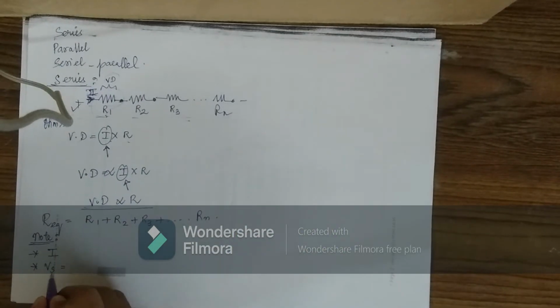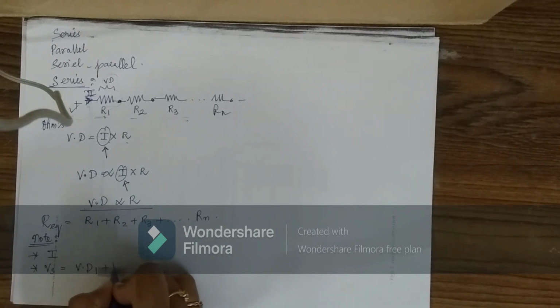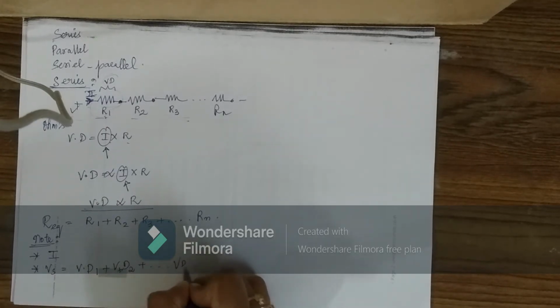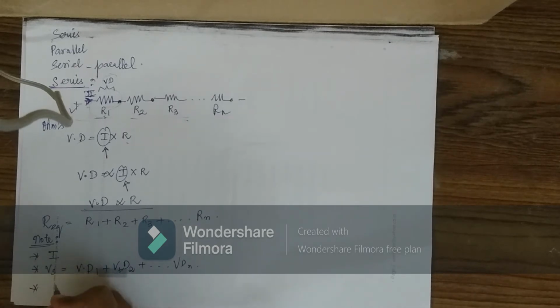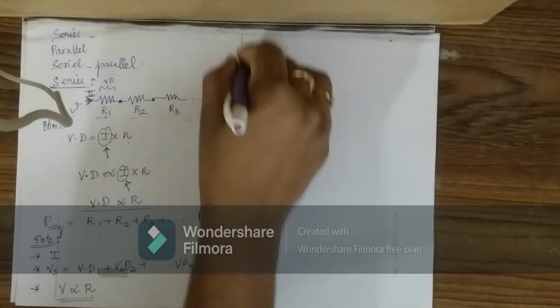So the applied voltage is the sum of the total voltage drop across each element: Vd1 plus Vd2, etc. up to Vdn. And the third point to be noted is that the voltage drop across an individual component is directly proportional to its R. So in series resistance, the voltage drop is directly proportional to the resistance value.